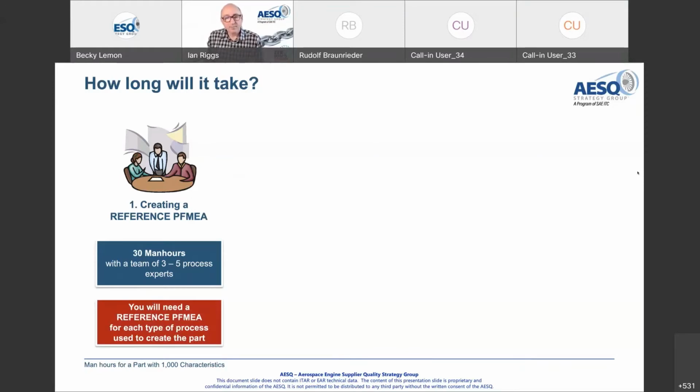Normally, that should take around 30 hours. From our experience, whether it was a welding operation, a machining operation, an assembly operation, 30 man hours using 3 to 5 people is how long it will take to create that reference FMEA that you're going to put into your library.